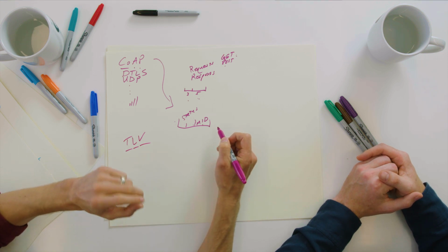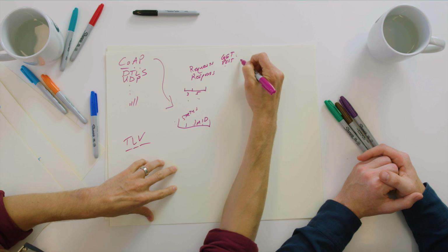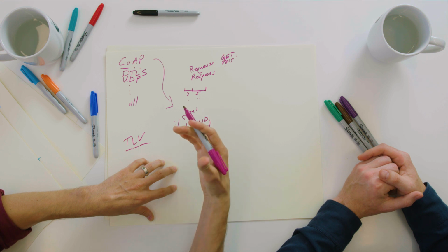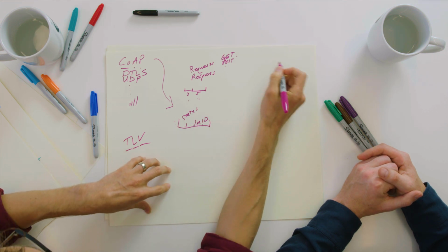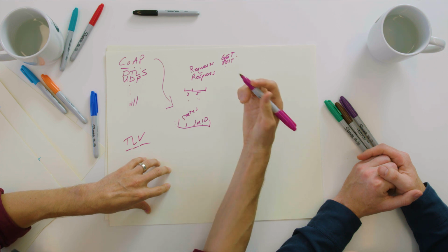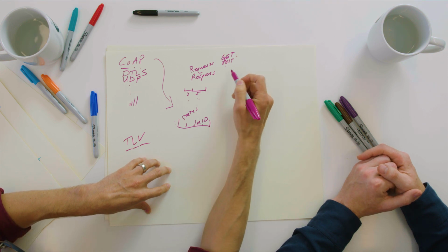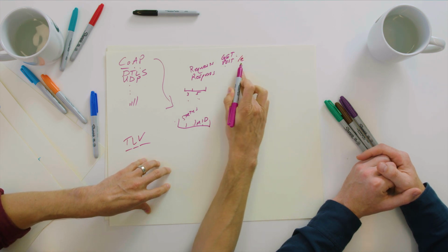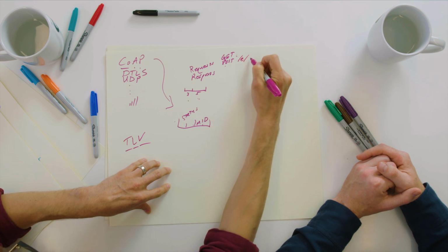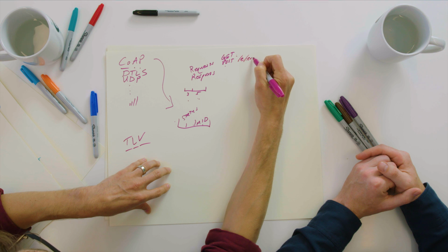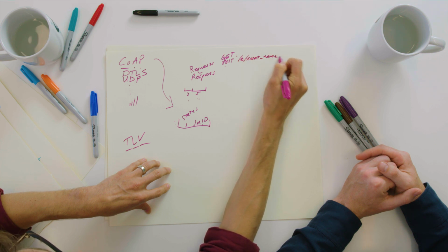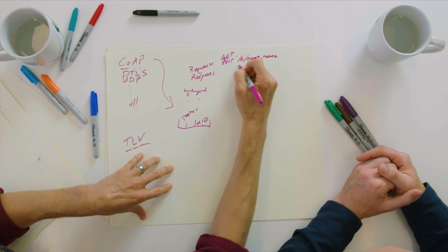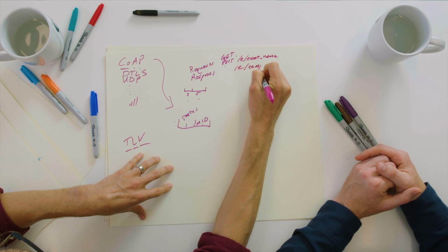So if you want to add one element, let's say in our Device OS you're publishing an event. You're saying, I'm reading the temperature and I'm publishing a temperature event. I'm saying the temperature is 60 degrees. And the way that we do that under the hood is with a CoAP message that's post /e, so E for event, slash whatever the event name is. So post E, and then whatever in your user app, say it's a temperature event. So let's say it's E /temp.